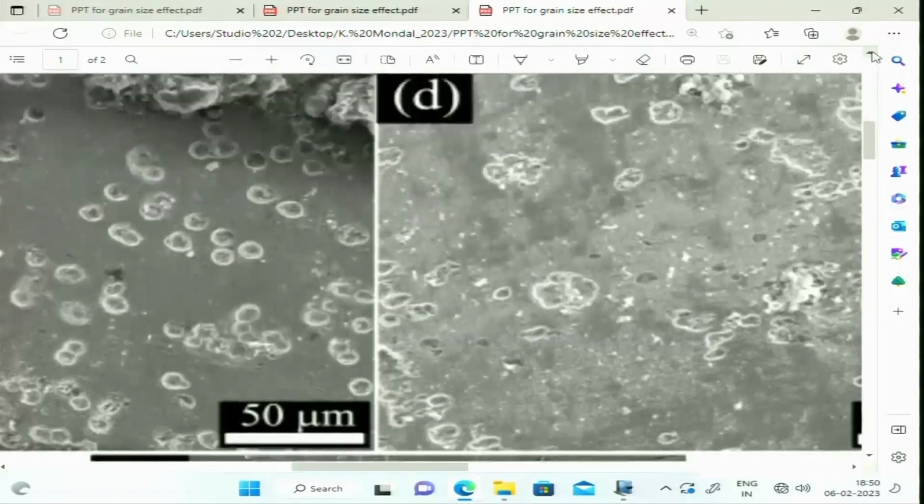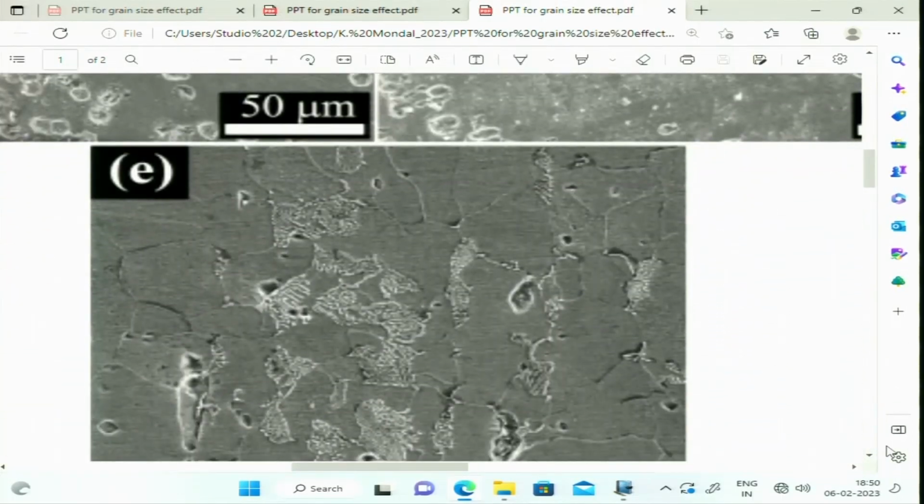So, similarly for the fine grain the same observation can be noticed. So, it clearly reflects that grain boundary sites are basically the initial attack sites. Now, the question is what we have observed in that paper. What we have observed is that this particular material in 3.5% NaCl solution did not show any passivity. It showed active behavior all the time, and in some cases we saw both cathodic and anodic processes are activation controlled, and in some cases the anodic process is definitely activation controlled, but the cathodic process could be concentration controlled. So, both are possible, but it does not show any passivation, and we have also seen that the 4 micrometer grain size material has the highest corrosion rate, and as we increase the grain size, we could see that the resistance to corrosion in 3.5% solution also has gone up.